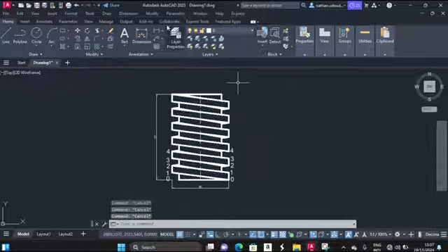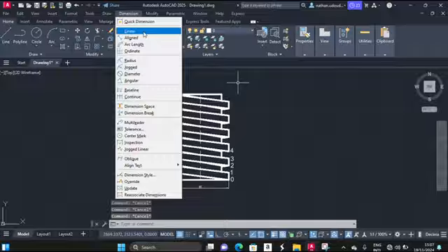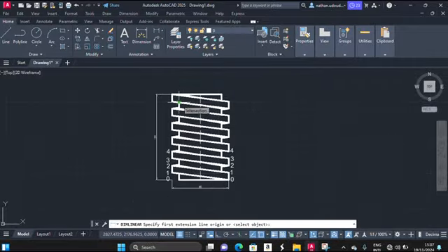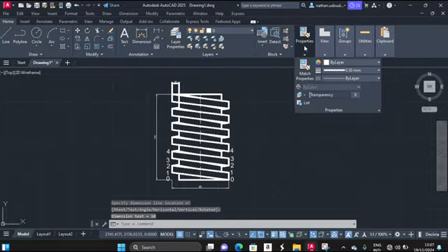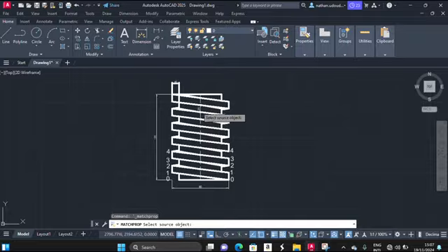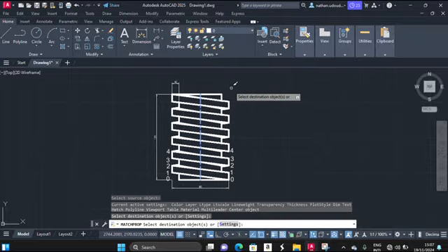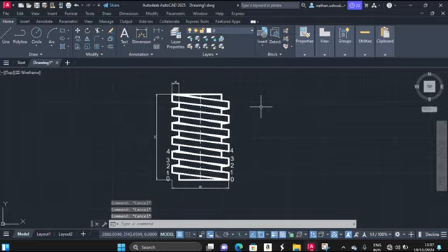Okay, so now you can also dimension this to indicate the distance, half of your pitch. So now come to your mesh properties and then this is 10. So once you are done, you print, Control P.